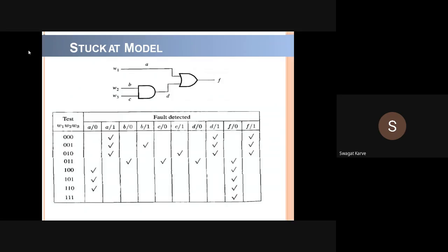Means now, second step, you have to identify the internal connections in that circuit. This is the second step. Right? And now, how to carry out the testing of that circuit? Now, you have to connect each and every connection manually either to a logic 0 or to a logic 1. You have to consider that it is connected permanently to a logic 0 first, then connect that same pin to logic 1, then check the output.